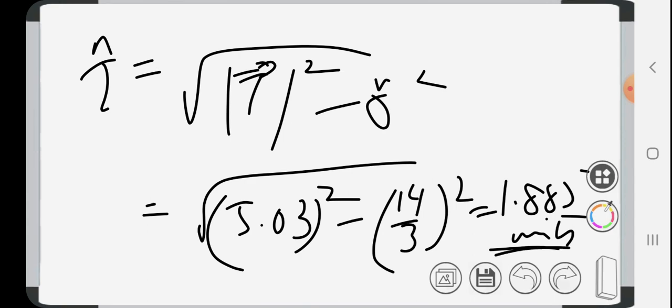So students, this is how we calculate a stress vector in an arbitrary plane whose directional cosines are given. If you have the directional cosines and the state of stress at that point, you can calculate the stress vector in that particular plane. You can have the XYZ components and also the normal and shear components. So this is the method to solve this kind of problem. In the exam, only simple problems will be asked, so don't worry. I will give some more problems as assignment, so try to solve them on your own. Okay.